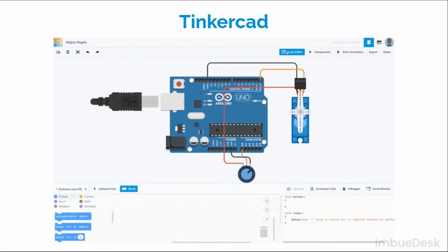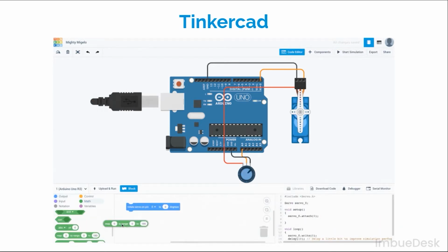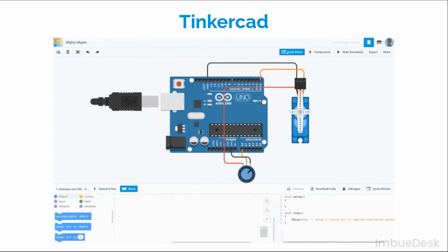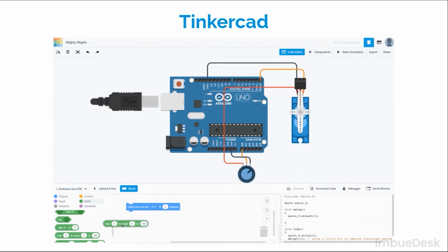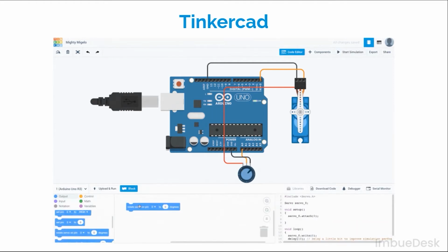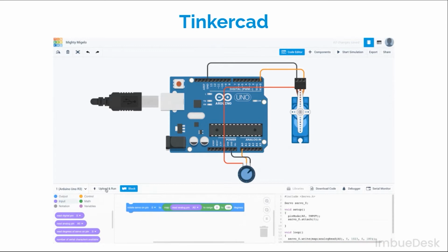So in the GIF, they coded Arduino in such a way that whenever we turn the potentiometer and alter the voltage received by Arduino from GPIO pins, then the servo motor turns. In a similar manner, we can operate many other sensors in Tinkercad.